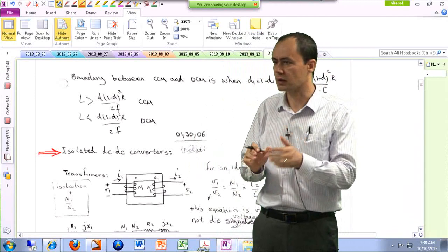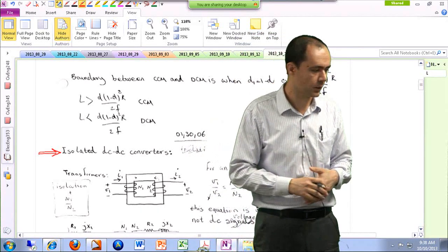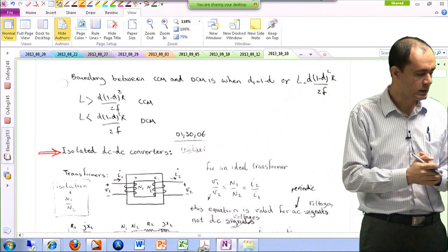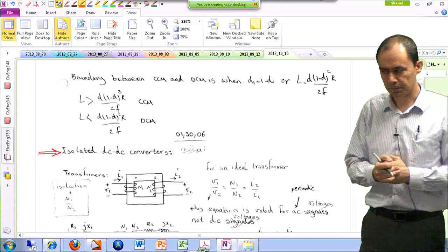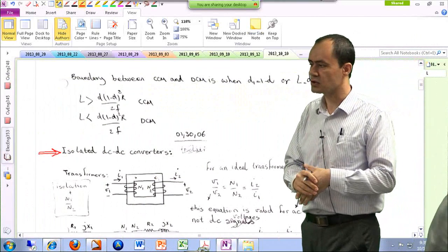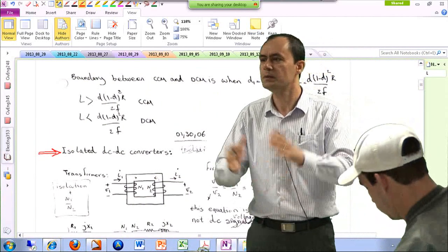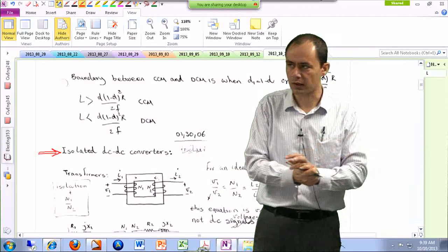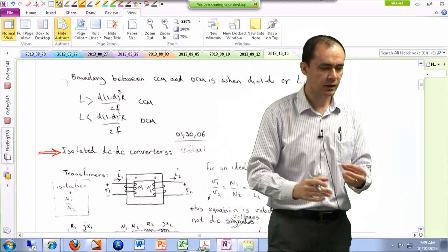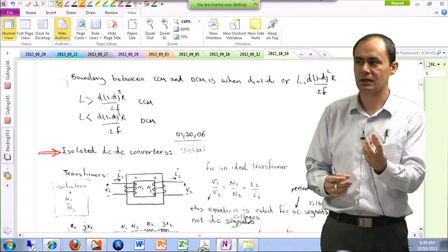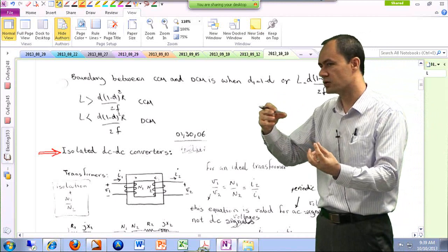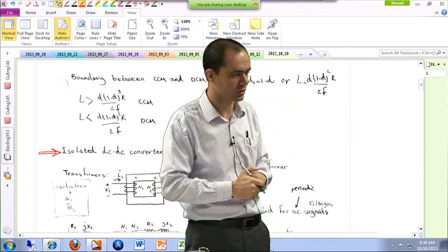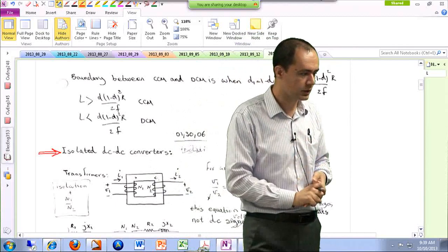So you should have some sort of an isolated DC-DC converter in there, or rectifier over there. So one is safety. And the other reason could be the product itself requires isolation. For instance, the product is in two pieces. Think about an electric toothbrush, okay? The primary side of a transformer is in the base, and the secondary side of the transformer is in the toothbrush, and they are not physically touching each other. I mean, they're not electrically touching each other. So that could be another application.